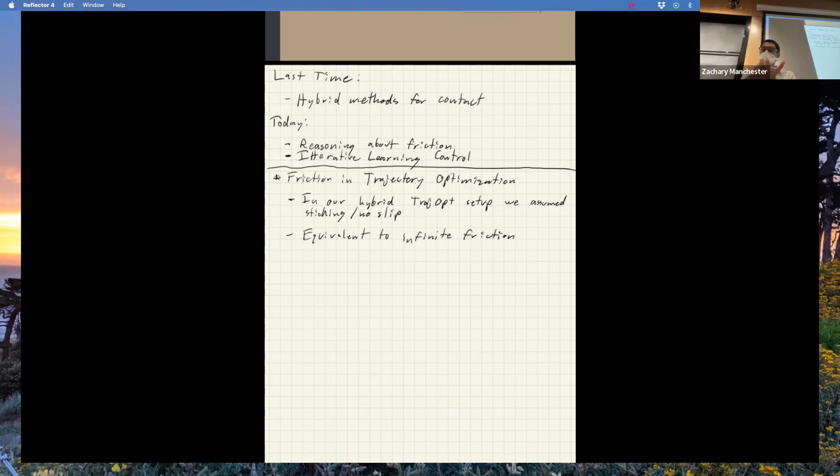In particular, in the friction case, the stick-slip transition is non-smooth, right? It's like if I'm pushing on a brick, push, push, push, at a certain point, all of a sudden it breaks free and starts sliding, right? And imagine if it's sliding, all of a sudden it just stops, right? So how do we get at that? It's very similar in a sense to the impact story. Non-smooth, gradients are not nice, blah, blah, blah. So we have to play similar games to reason about friction as with impacts. And there are some standard tricks. So we'll talk about a few of those tricks right now.